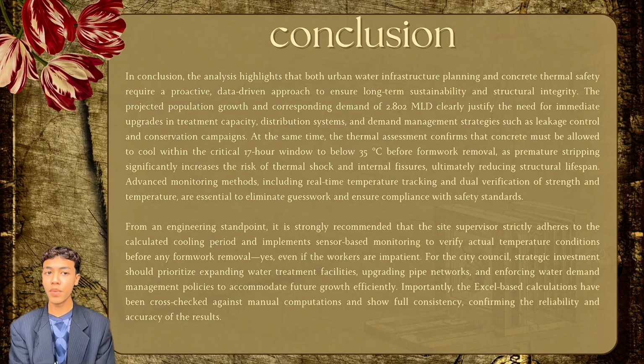So, removing formwork too early subjects the concrete to thermal shock. This sudden temperature change causes internal fissures where it can cause cracks. While this might not be visible immediately, they significantly shorten the structural life of the concrete.